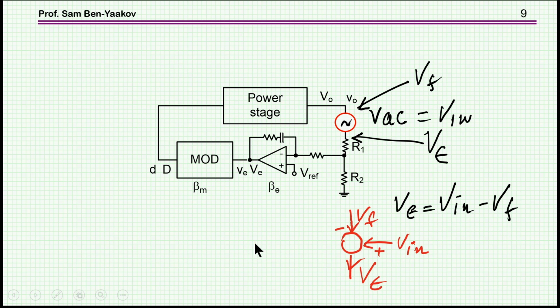What we can do is, within the feedback path, to inject or put in a voltage excitation source. This is an AC source with an internal impedance of 0 or very close to 0. And this source actually acts as a summing point, because the voltage here is the sum of this plus the voltage itself, that is this minus this, you might say, is equal to this.